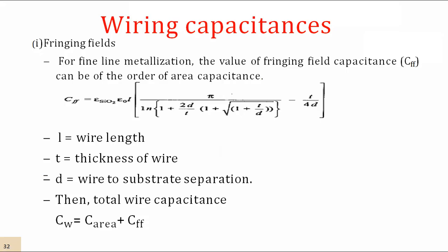Like that we have calculated the different areas for the capacitance. In the previous example, the area capacitance was associated with the layers to substrate and from gate to channel. We have calculated that area. However, there are other significant sources of capacitance.